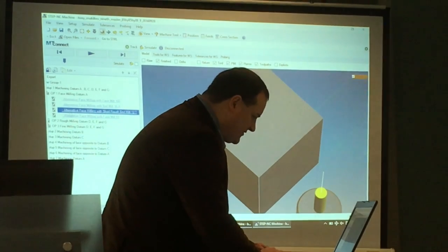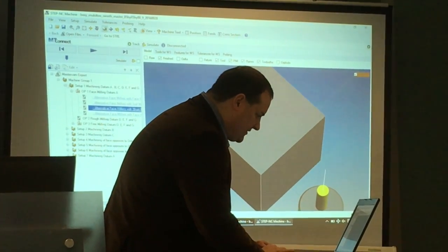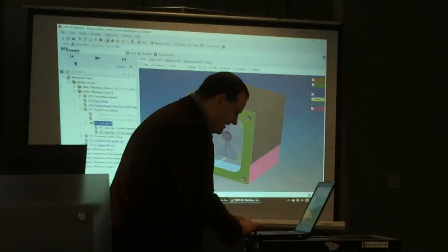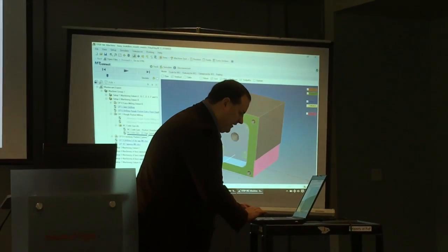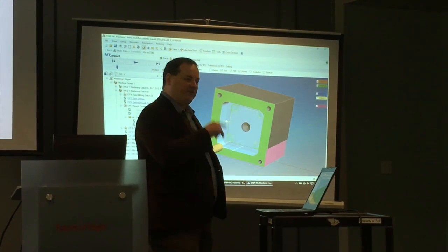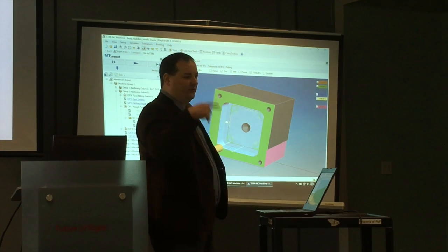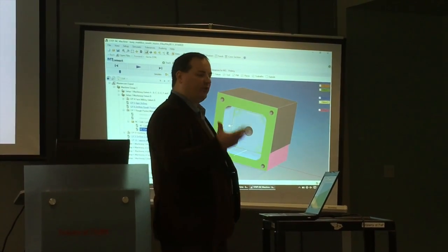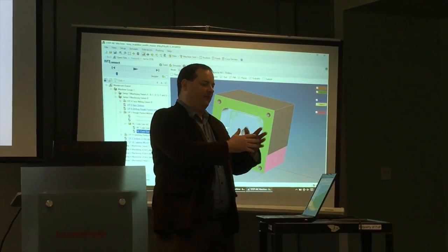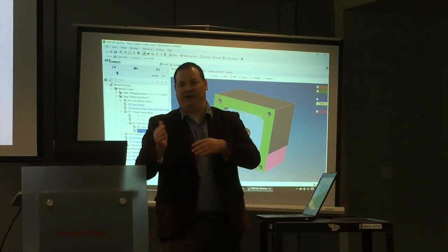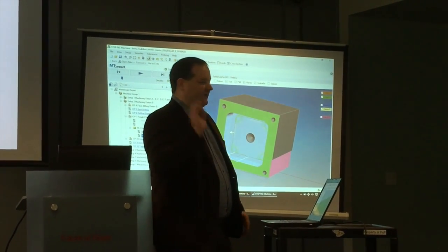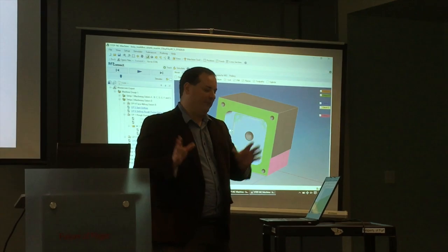I'm now opening the modified solution, navigating back to setup 2 in that pocket. And we'll see we now have a third option, suitable for titanium. We have a bulk removal operation and a corner cleanup and finishing operation. We are using MasterCam to generate the actual tool paths, after we have an internal representation of an operation that's sort of agnostic to the CAM system. And then we more or less do a mapping from our operation to a MasterCam operation, copying parameters into semantically equivalent fields of a MasterCam operation. And then we kind of hit the easy button and say generate toolpaths for such an operation.